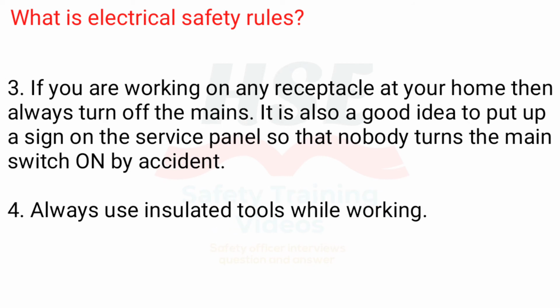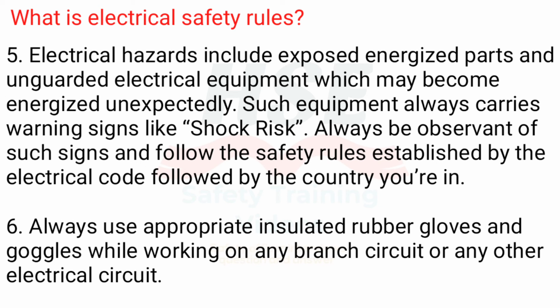3. If you are working on any receptacle at your home, then always turn off the mains. It is also a good idea to put up a sign on the service panel so that nobody turns the main switch on by accident. 4. Always use insulated tools while working. 5.